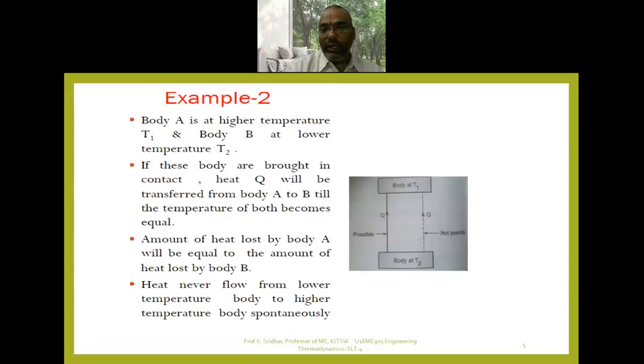So the heat is transferring. In which component are you able to get the cooling effect? It is the evaporator. The evaporator is the actual component which gives us the desired amount of refrigeration or cooling effect. The refrigerant flowing inside the refrigerator will absorb the heat from the products or substances we keep inside the door of the refrigerator. That heat is taken up by the refrigerant,